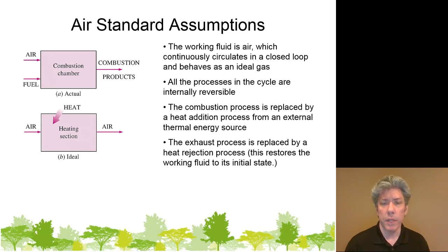Also, we will assume that that air behaves ideally, which is not a bad approximation at all. Another assumption we'll make is that all of the processes in the cycle are at least internally reversible. Now, not fully reversible like the Carnot cycle. Like I said, we're getting a little bit closer to reality, but they are at least internally reversible.